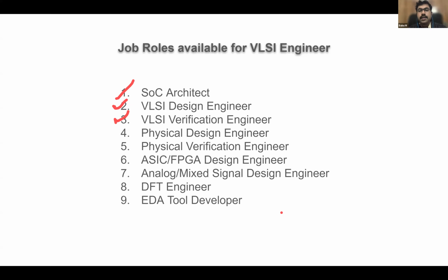Once the RTL design is ready, it is the role of the verification engineer to check whether the functionality intended for that particular chip is as per the requirement or not. If there is any bug, fault, or violation from the design, that needs to be captured by the verification engineer and reported back to the designer. The designer will work on that feedback and release new RTL versions. Again, the VLSI verification engineer needs to verify it and confirm that functionally it is good.